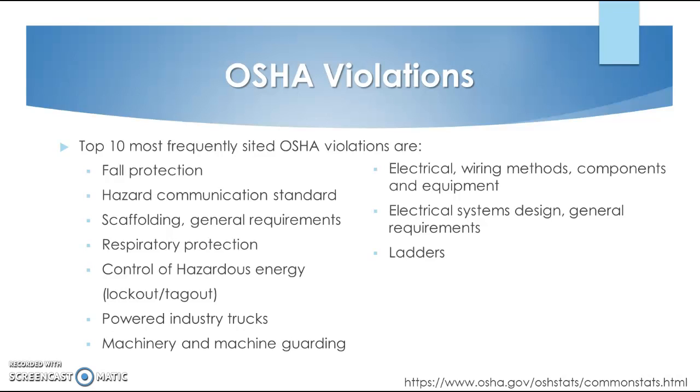Also, any non-conductive paint, enamel, or similar coating should be removed from threads, contact points, and contact surfaces, or be coupled by fittings so that removal isn't necessary. Employers also need to ensure that no wiring systems of any type are installed in shafts or ducts used to transport dust, loose stock, flammable vapors, vapor removal, or ventilation of commercial type cooking equipment. Not following the rules established by OSHA in regard to electrical and wiring will result in a violation.